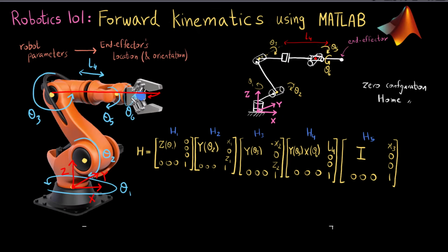Now when I change my theta 3, so theta 3 is this one right here. Let's say I make theta 3 go to 20 degrees. What would happen is my robot, this thing, would go down, right? Because I've taken theta 3 in this direction, which is counterclockwise. So it would go down, and this is 20 degrees, let's say. So positive 20 degrees would go down.